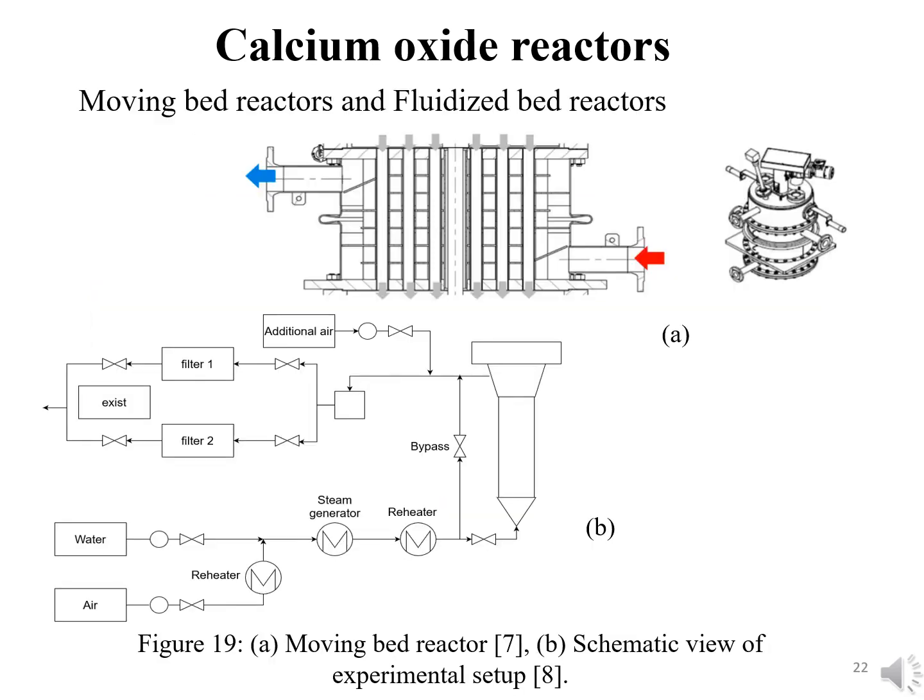In the moving bed reactor, the moving bed is believed to reduce the pressure drop and heat and mass transfer obstacles in a fixed bed. Diagram of the reactor is shown in figure 19a. This reactor adopts a counter-current form. Unreacted contact material enters the pipeline from the top and hot air enters the reactor from the bottom. Heat is transferred by a hot fluid that flows on one side of the heat exchanger cell and is guided by a baffle. These plates ensure rapid air circulation.